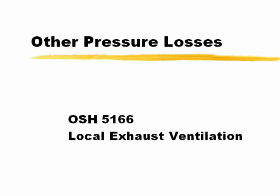Welcome to the recorded lecture for Module 3, and the goals of this recorded lecture are to provide a description of pressure losses that we may experience in a local exhaust ventilation system. So we've talked about pressure losses in terms of hoods, and as we move air through our ventilation system, through the hood, we experience some losses, and we just need to account for those losses in order to ensure that, at the end of our ventilation system design, we are selecting a fan that will overcome those losses and be able to deliver the CFM that we have prescribed for our system.